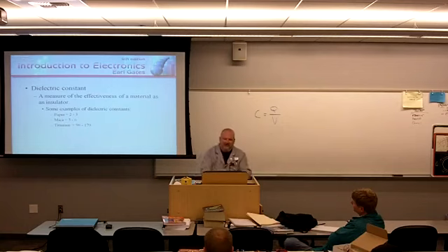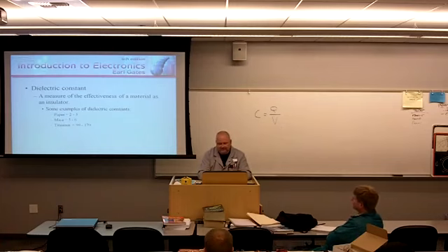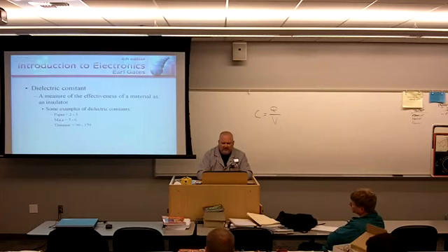I've restored a handful of radios, haven't replaced one tube. Got in there, replaced the capacitors. Why? Paper capacitors. What happens to paper over time? It deteriorates, loses its dielectric constant, the capacitor shorts out, doesn't work. Mica, dielectric constant between 5 and 6.